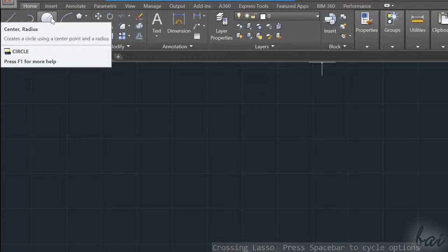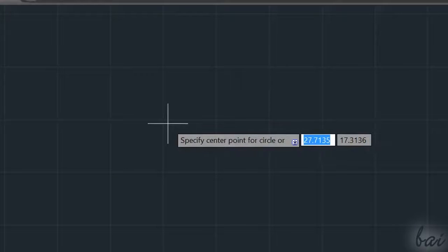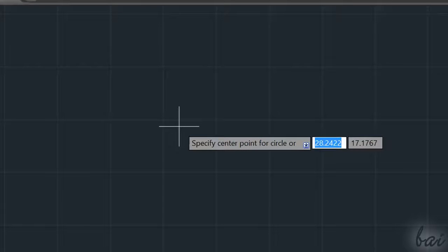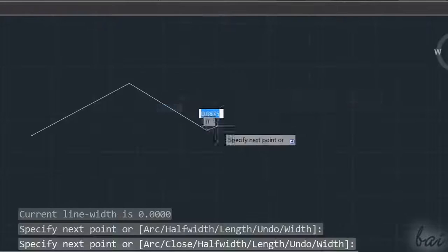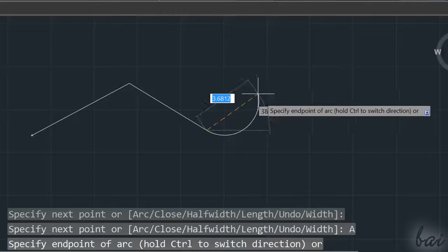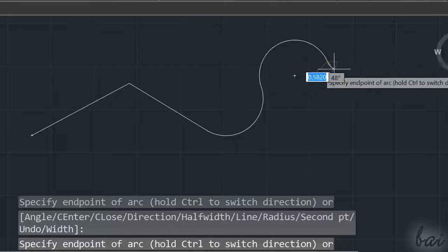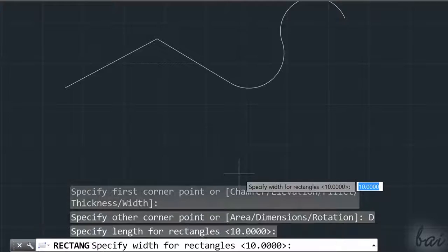There are lots of options that can personalize your current tool enabled. For example, while you draw, there is a dialog box beside your pointer. If you use your down arrow key, you will open its options inside that do change depending on the tool you are using. Through the up and the down arrow keys, you choose in this list and use the Enter key to apply. So, if you draw a polyline, you can go to Arc to draw an arc instead of a straight line. If you draw a rectangle, you can fix it by defining area or any length.